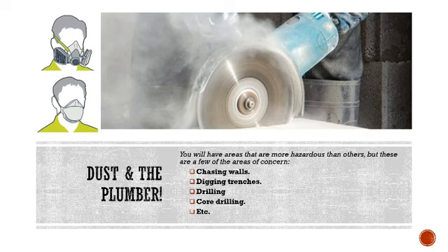This comes with its own individual hazard. For one, the dust is going to be circulated in and around that area without a very good means of escape, especially if we haven't made room or allowance for the extraction of that dust. Now, another thing we need to consider when chasing walls is, as soon as we have the dust inside the room and we extract that dust, where are we pumping it to?